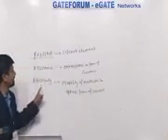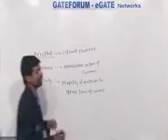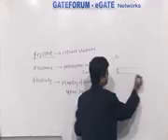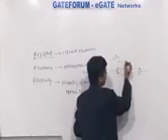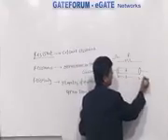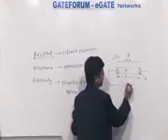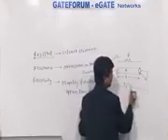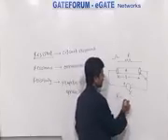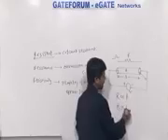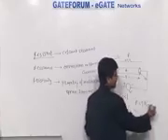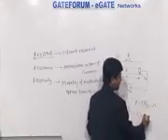So whenever we talk about resistor, resistance and resistivity, the unit of resistance is nothing but ohm, where I can say that I have some resistor having value R, this is length L, area of cross section is A, and some excitation is given to this. Then I can say that resistance of any material is proportional to length of the material and inversely proportional to area of cross section. R is equal to rho L by A, which is given in ohm. Therefore resistivity is given in ohm meter.